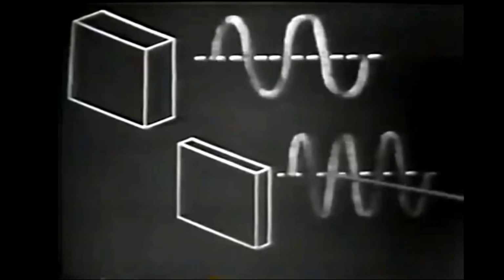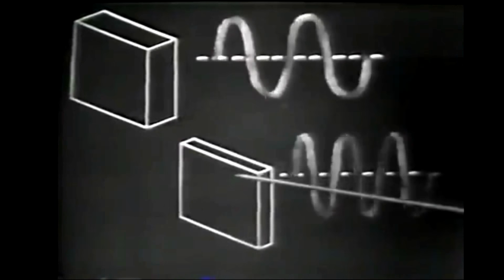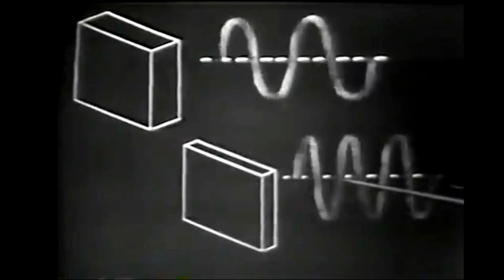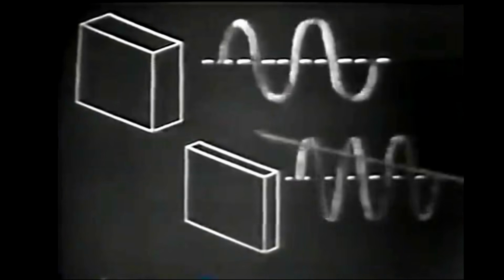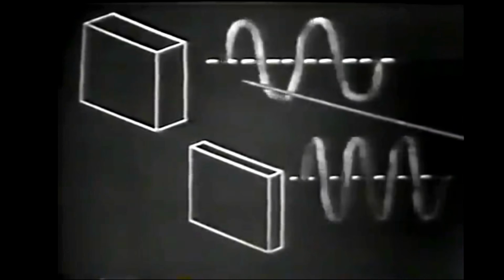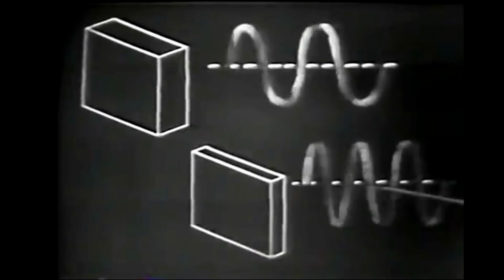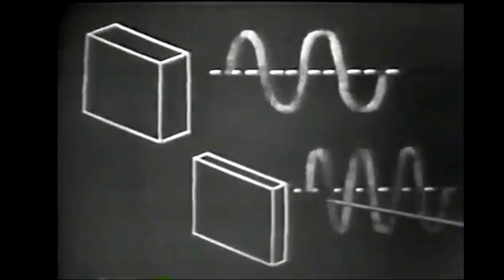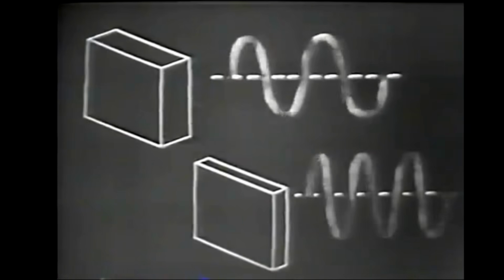We're indicating here that the vibration of this thinner cut, or the frequency, is greater than this cut. Now, this will always hold true. The thinner the crystal cut, the higher the frequency of oscillation. Now, there are a few other crystal cuts with better frequency stability, but these will not be discussed in this lesson.